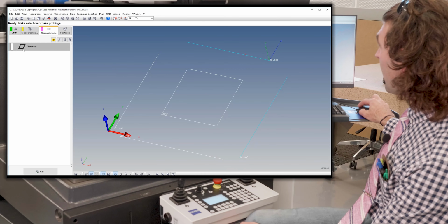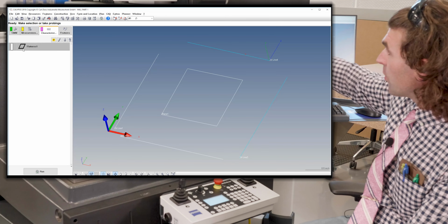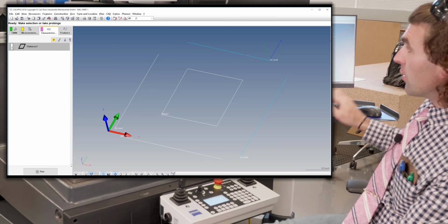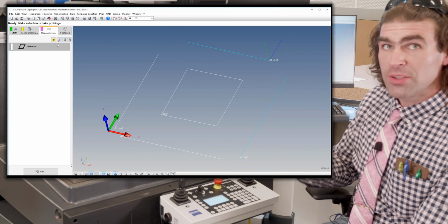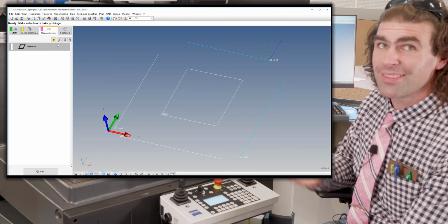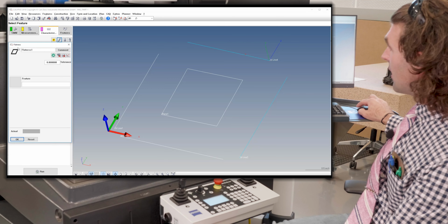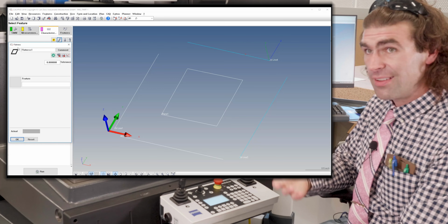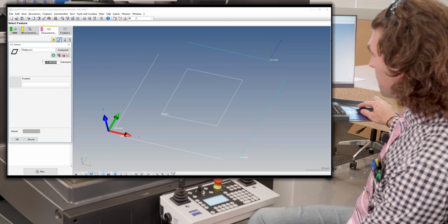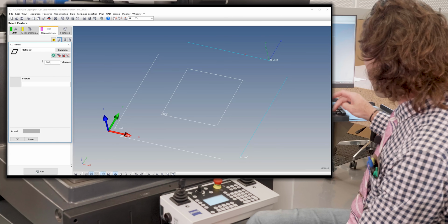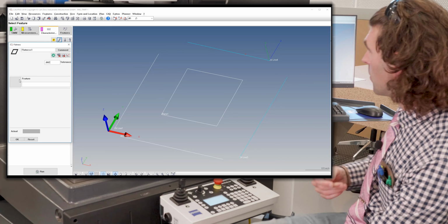So I'm going to go to Flatness. Now it brings us to the Characteristics tab. If you notice, there's a little gray box next to Flatness. That means it hasn't been checked, it's not programmed, just totally blank slate. I want to go to the pen tool right here, open selected object. It brings us to the Flatness dialog box. The first thing I want to do, because it's easy to forget, is punch in the tolerance. So it's 2 thousandths, so decimal place, 2 zeros, 2, okay?